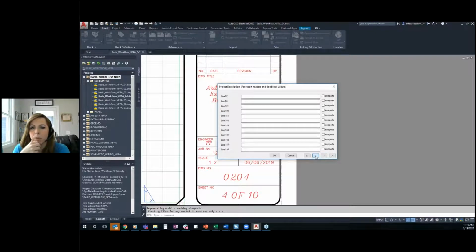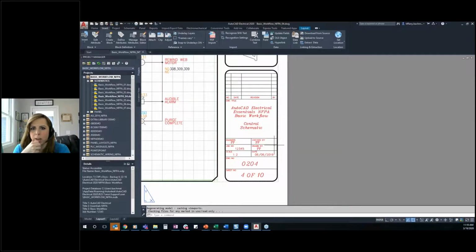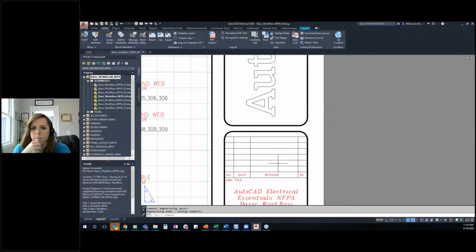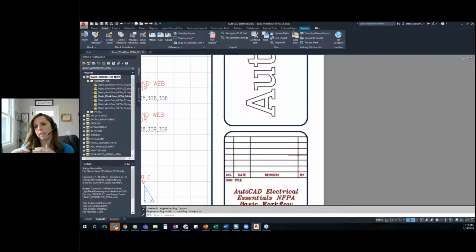We often rev at a project level, so I would typically tell people to just do that here. If I were to build this revision table up here with all the attributes that I need and just put them into that list, then I can update that and have as many attributes as I want updated back into here. That would be the core AutoCAD Electrical functionality for a revision table. Now, managed from a Vault standpoint, I'm going to let Matt take that.